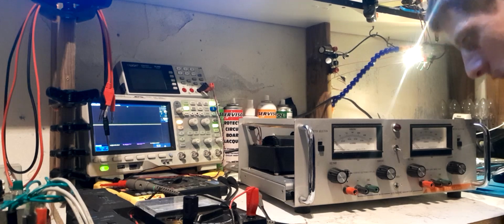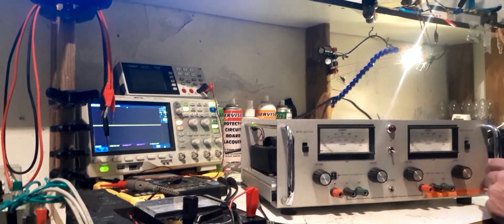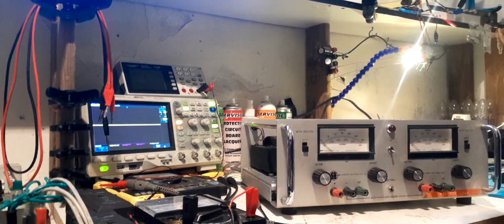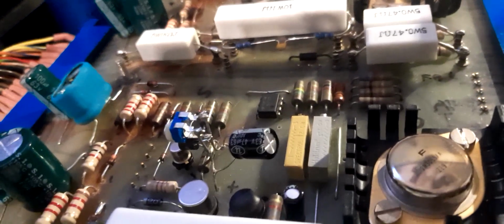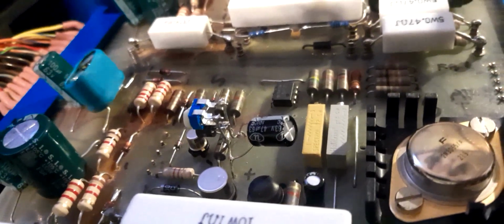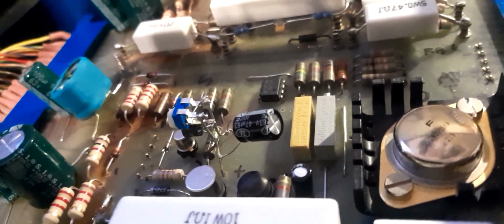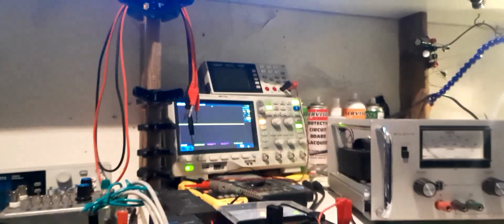Actually, what I think I'll do, because I'll just give you guys a quick look, because I've got this dead bug style TL431 with a pot on 2 pins and a cap tacked off of it. I think I'll just cut the pins and solder a Zener on top of it, because you guys have seen how old the board is.